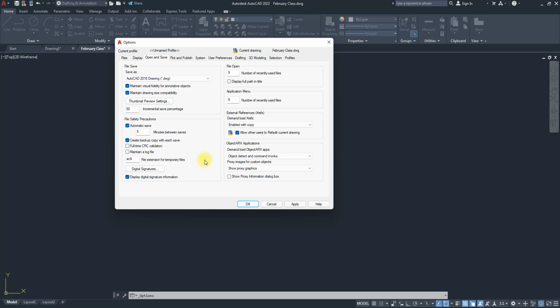The backup file that is going to be created for you will have an extension of .bak. The benefit of having that .bak file is that there are times when your file will get corrupt and you cannot retrieve it, even though Recover can allow you to recover some things. There are some files that you cannot recover, but the backup is another way of recovering these files. Anytime you have a file that is corrupt, all you need to do is go to the backup of that file.